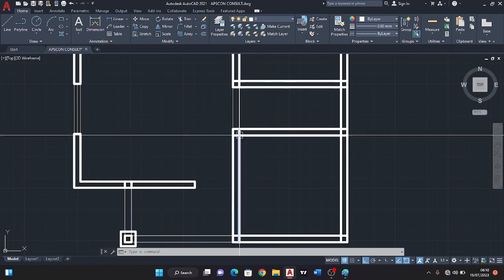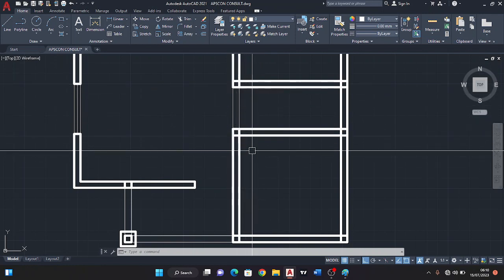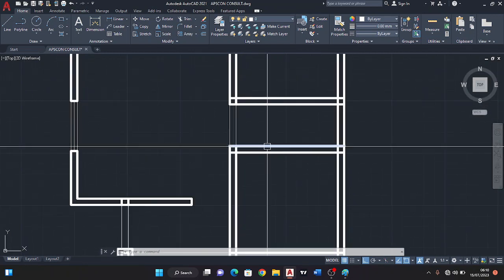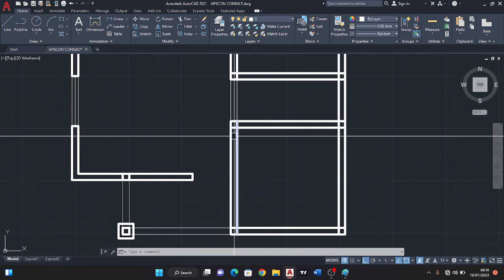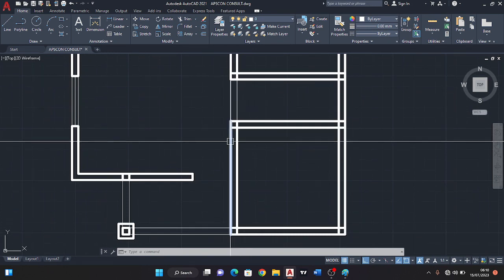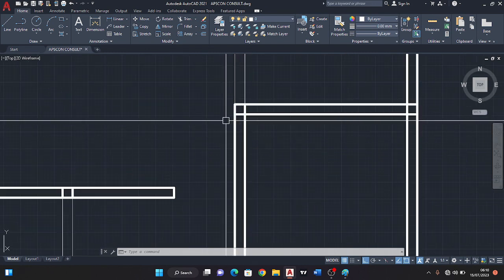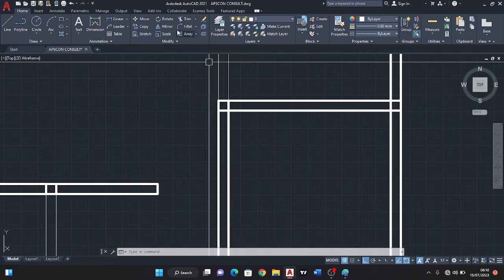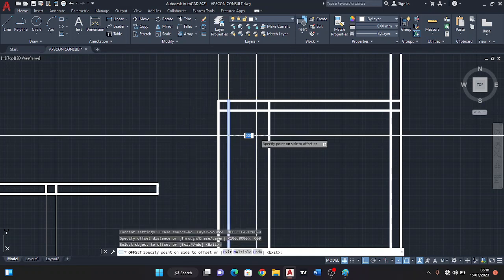So I don't want them to have an opposite connection, like they face each other, to control our ventilation and also some privacy. Now I've decided to put down my kitchen door here, but before the kitchen door, I don't want the door to just be directly at this wall. I'll create a small inner space of, let me say, 600 before I'll place the door.